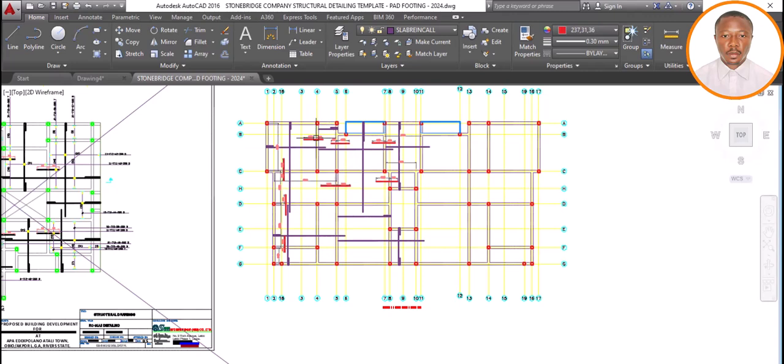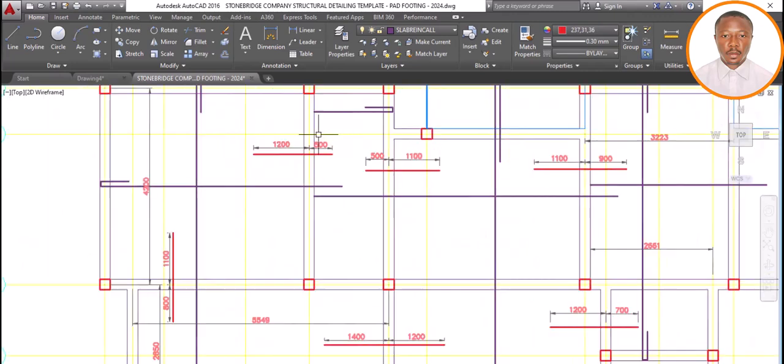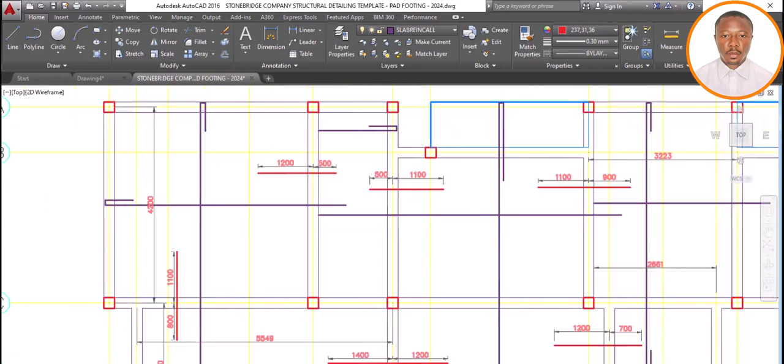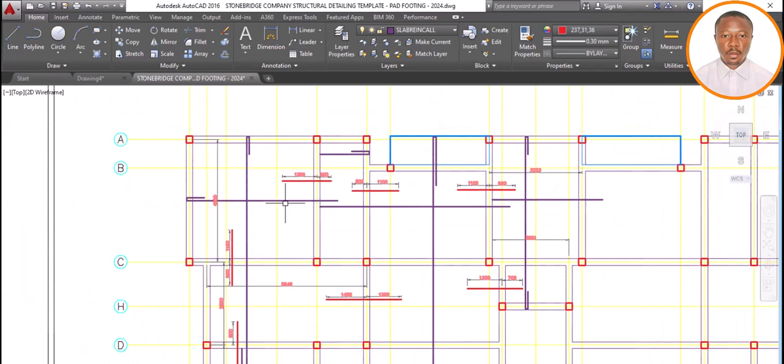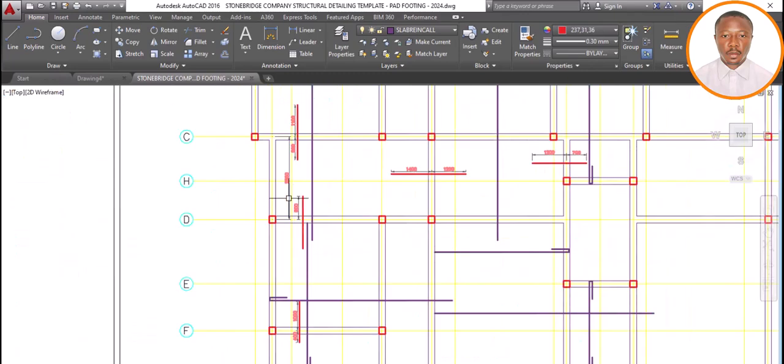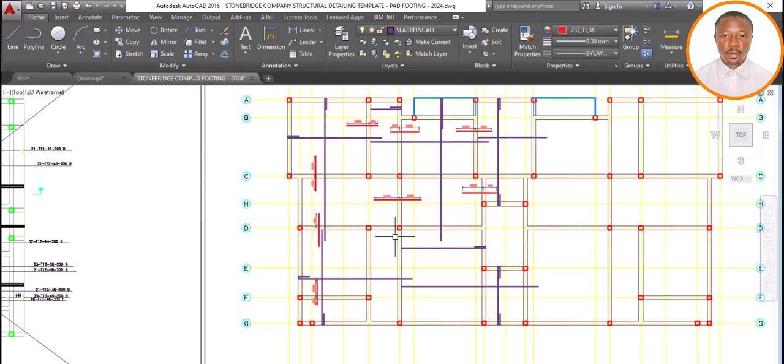As you can see, we have finished indicating our top reinforcement, and the principle behind it, which is that 25% of your slab length will become your top reinforcement into each slab. So let's remove all these dimensions. We don't need them. Now you can see how clean it is compared to what Prota detail gave us last time, how Protastructure normally brings out the slab detailing, which is not actually good at all.